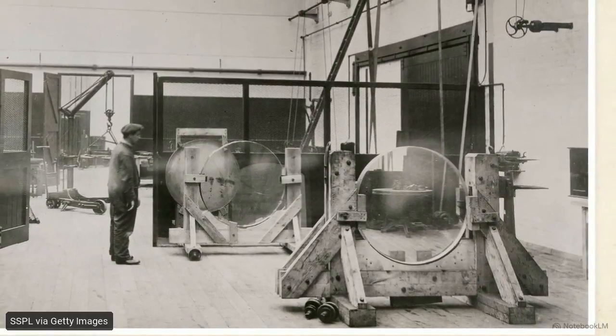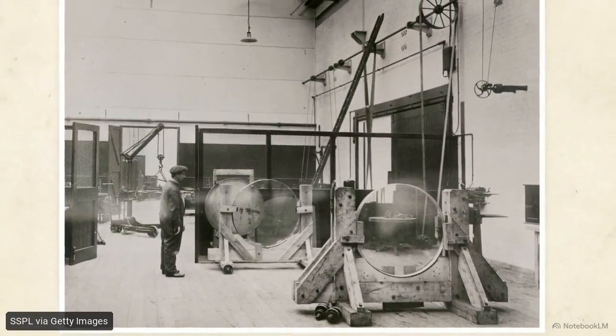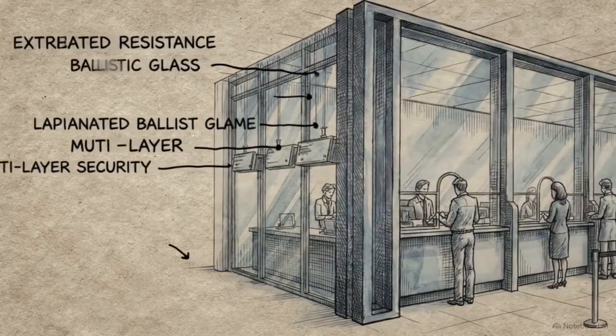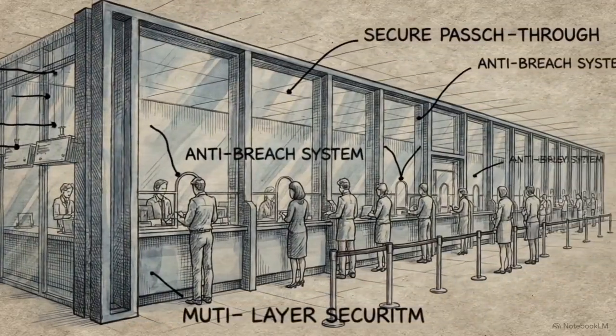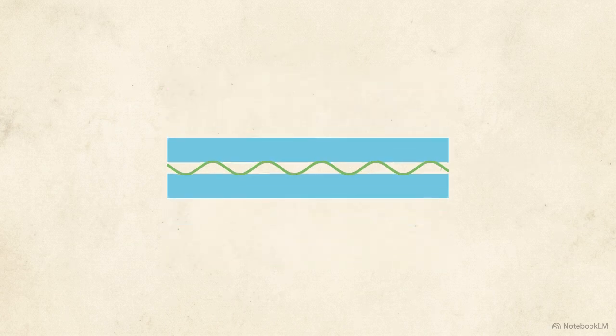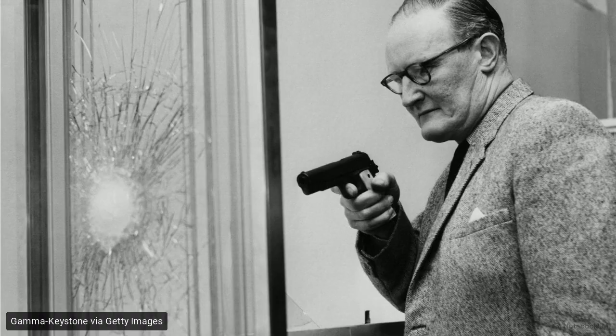If you need to manipulate light for specialized photography or industrial sensors, you require optical glass. By mixing in phosphorus and cerium oxide, the material is engineered to specifically absorb incoming UV rays while refracting visible light perfectly. Then there are environments built around extreme physical security, like jewelry store displays or high-volume bank teller windows. In those scenarios, chemical hardness alone isn't enough to stop a projectile. They deploy bulletproof or laminated glass. This is manufactured by placing flexible vinyl plastic between alternating layers of glass, then tightly pressing them together. When struck, the outer glass breaks, but the inner plastic stretches to safely absorb the kinetic impact.